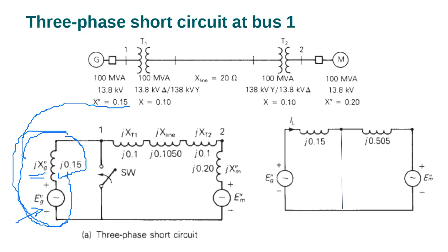And then we go on to bus number 1, so we write 1. Then what do we do for the transformer? Don't forget the transformer here is 0.1, so we put 0.1. Remember, after we convert into per unit, in this example the base is 13.8, and it works all the way, so we don't need to modify any reactance.